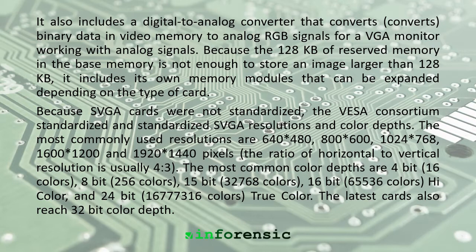Because SVGA cards were not standardized, the VESA consortium standardized SVGA resolutions and color depths. The most commonly used resolutions are 640 x 480, 800 x 600, 1024 x 768, 1600 x 1200 and 1920 x 1440 pixels. The ratio of horizontal to vertical resolution is usually 4:3.